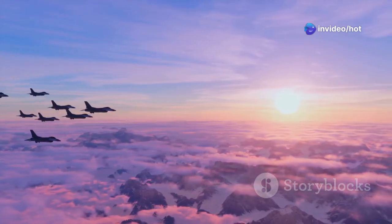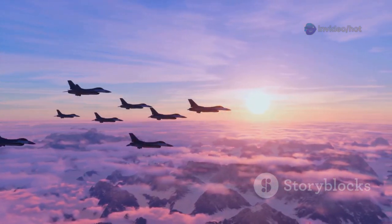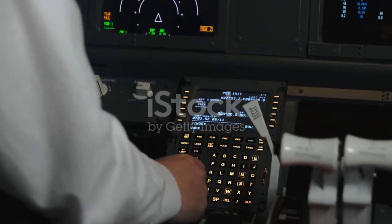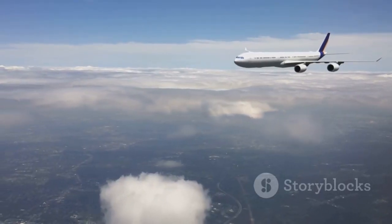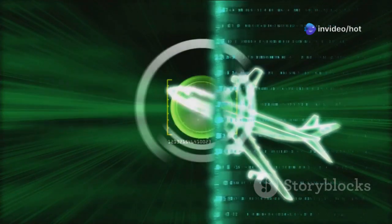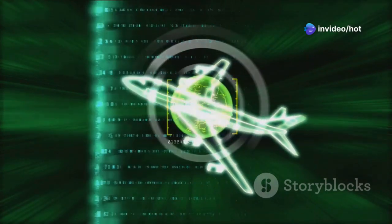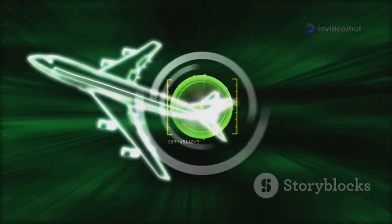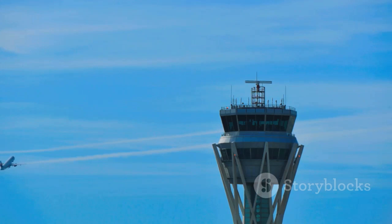Section 9, Conclusion, Vertical Separation, the bedrock of air safety. The allocation of flight levels is not just a technical detail, it is a cornerstone of modern aviation safety. The semicircular and quadrantal rules, though simple in concept, provide a systematic way to organize air traffic vertically. They are the first line of defense against mid-air collisions, ensuring that aircraft on different tracks have inherent separation.